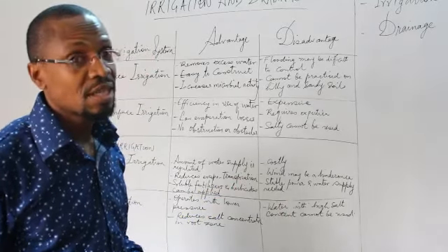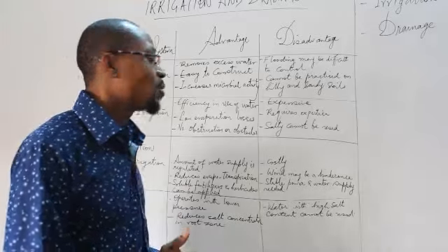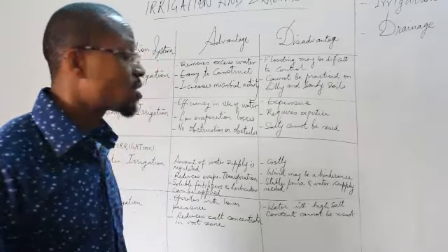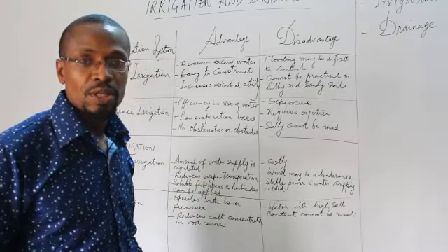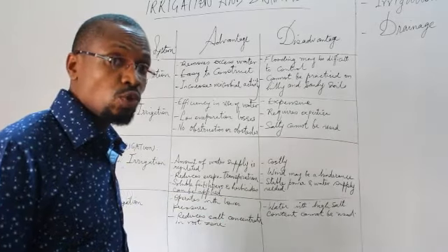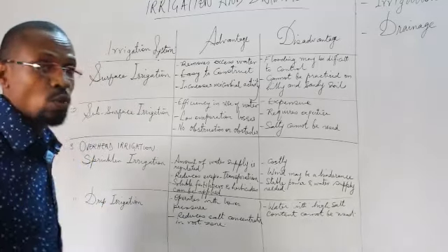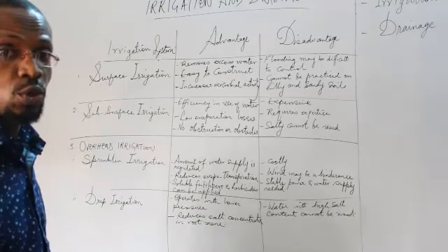However, this method is expensive. You have to note that. It requires expertise, and salty water cannot be used. Salty water cannot be used because the water goes directly to the roots of the plants, so salty water will be injurious to the plants.